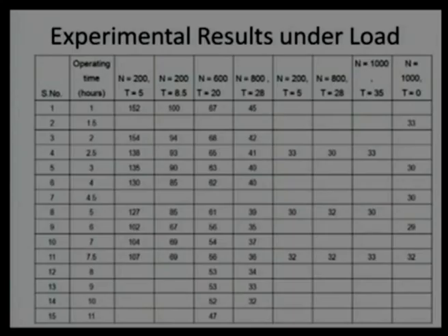When we study this boundary lubrication mechanism, we are able to understand the mechanism in a different manner. Even though we know the bedding in behavior, the wear rate should be very high initially, it should reach a steady condition and after that it should increase. While in this case, bedding in time shows that running in behavior is changing with the speed and changing with the load condition. That is why we need to understand the system completely.